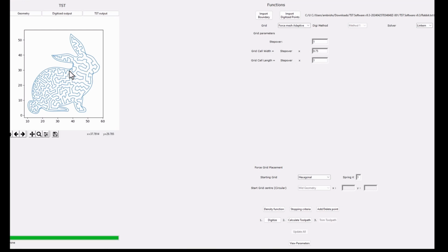So in this adaptive grid, what you have is the contour, and there are two directions. The one direction is where the toolpath is perpendicular to the contour, and the other direction is where the toolpath is parallel to the contour. If you are familiar with contour parallel toolpaths, there could be two directions. Either you are perpendicular to the contour, or you are following the contour parallel to the contour. So there could be these two directions, and you are biasing the toolpath in these two directions.